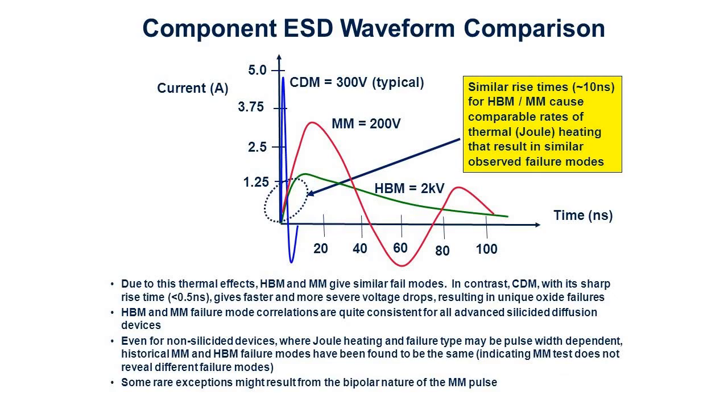The test limits for the ESD charging voltages increased within the last years up to 25 kV and more. At the same time, shrinking dimensions and higher package density lead to more endangered electronic devices. The demand for more functionality in automobile electronics causes a rising number of electronic components. These components are connected via the car cable harness. Hence, the damage potential by ESD events increases.